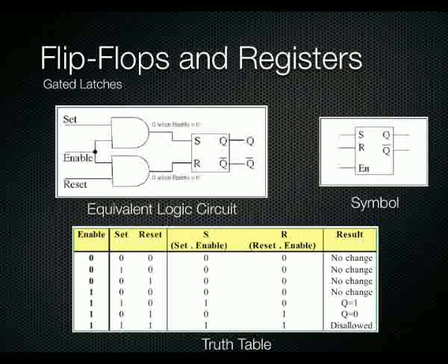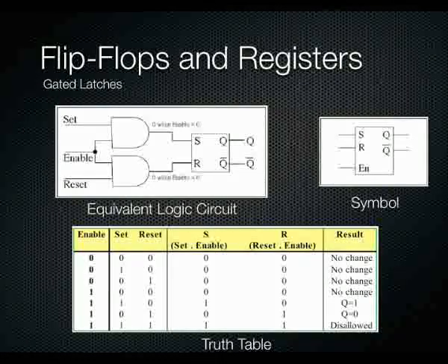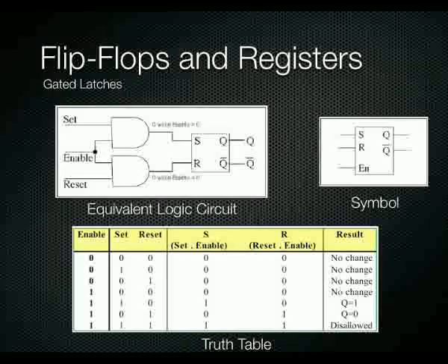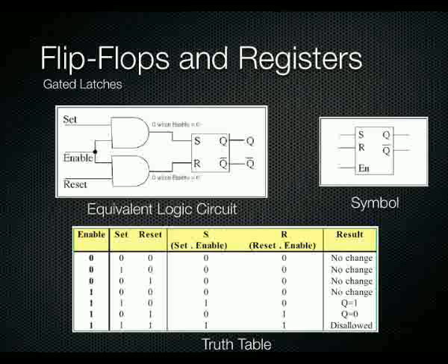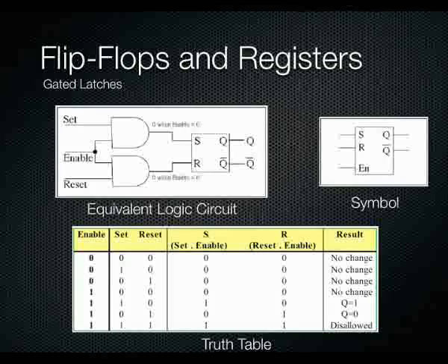If you look down at the truth table, you can see that as long as the enable is set, set and reset happen normally. When the enable isn't set, then of course nothing happens, no change. The RS latch doesn't actually change in any way unless the enable line is high.